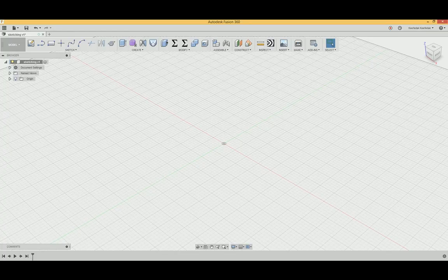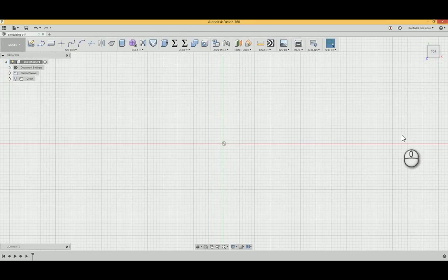Now, we're going to do a whole bunch of stuff in Sketch, and we're going to focus on constraints. Constraints and sketching, that's the rock solid bottom foundation of modeling. Now, we're going to start sketching at that cube where you see the word top on top of that cube. Click it. What happens? That whole page is going to come like it's laying flat, okay? And you're going to see the top of the cube.